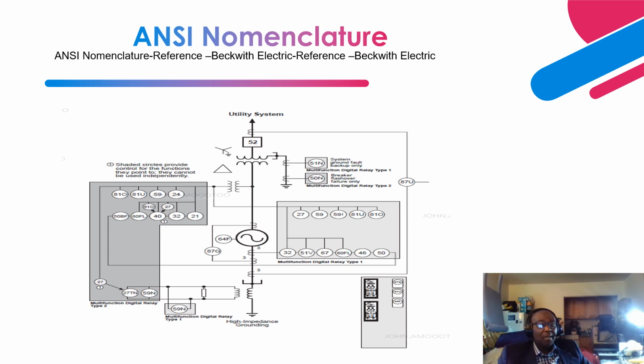So the next element is 87G. This is the differential protection. This is the main protection system for the generator. You have CTs at the terminal of the generator and CTs at the neutral of the generator. So it's measuring the difference in current.